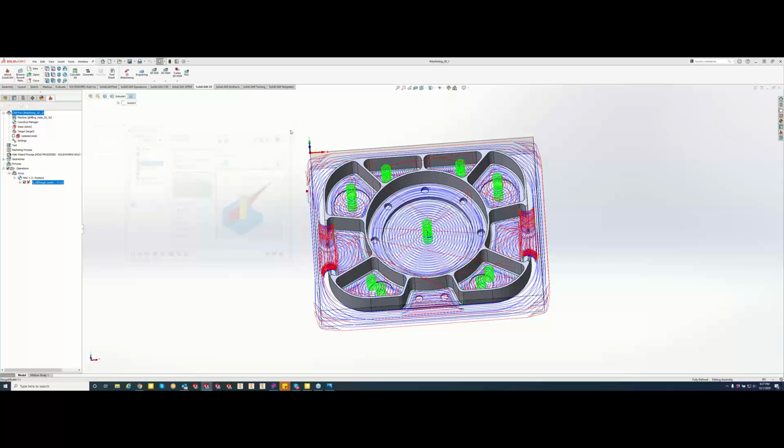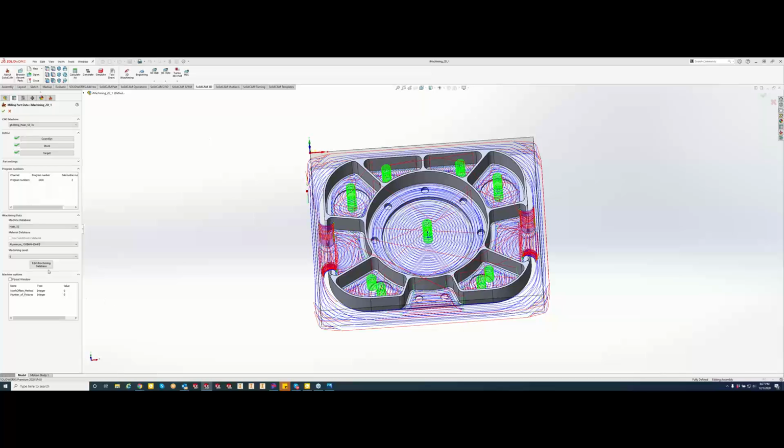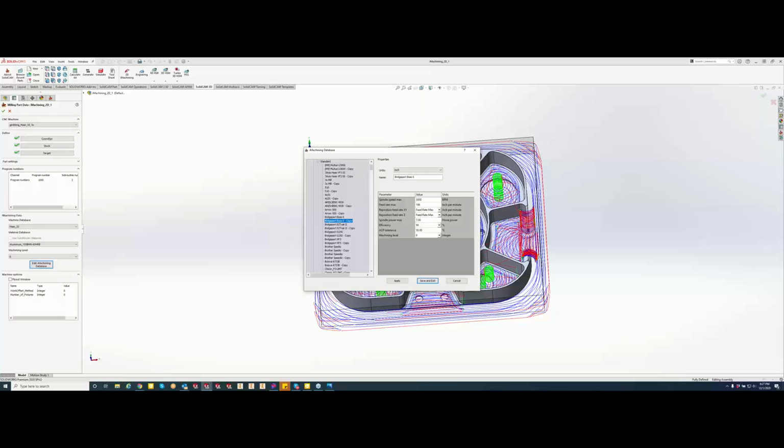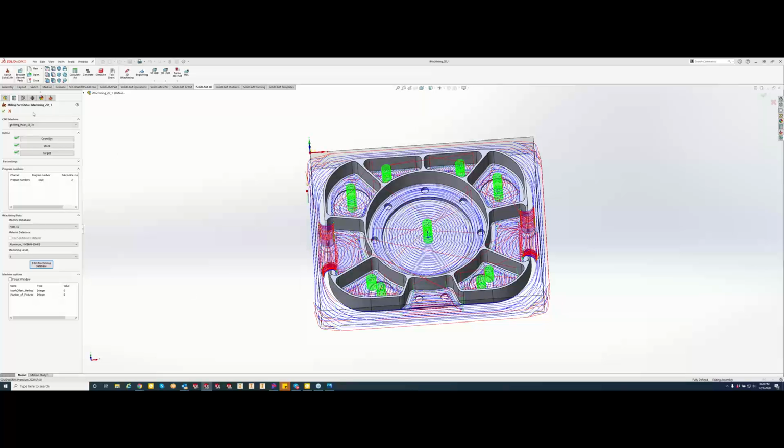Yep. And to show you where that is for everyone, if we go to Edit iMachining Database, right here you can see the ACP tolerance. By default, I think it's set up to 20%. Yep. Some, like the Sharpen, are set to 15, depending on the machine. Now a Haas, I would assume that's going to be, yeah, we got 50%, and this is on the Haas tool room mill. So it definitely depends on the rigidity of your machine there. Great point, Greg.